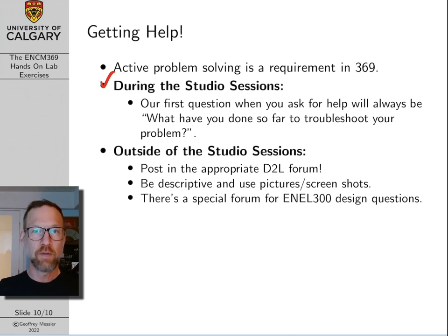So let's say, for example, your programmer is timing out with an error, right? There is literally a timeout error. And we might ask you something like, oh, well, is the power properly hooked up to your chip? And you're like, well, I'm not sure. Okay, well, why don't you take your multimeter and check to make sure that 5 volts is present at all the pins where there should be 5 volts. What about your ground pins? Are they hooked up to ground? Yeah, they are. Okay, well, great. So it's probably not power.